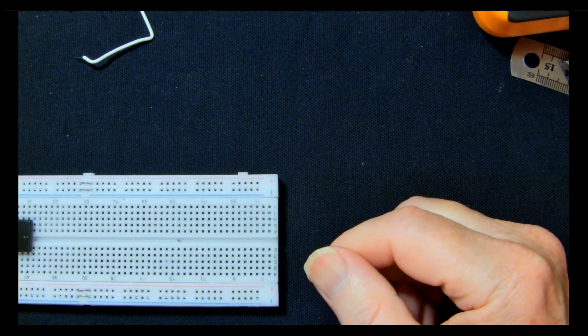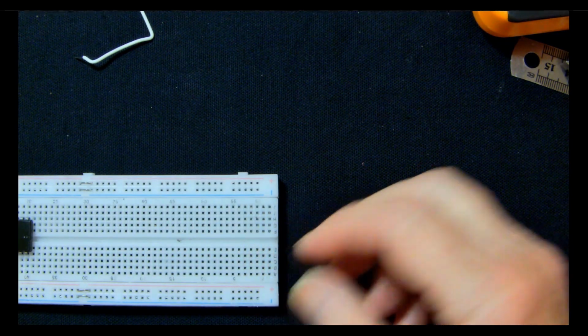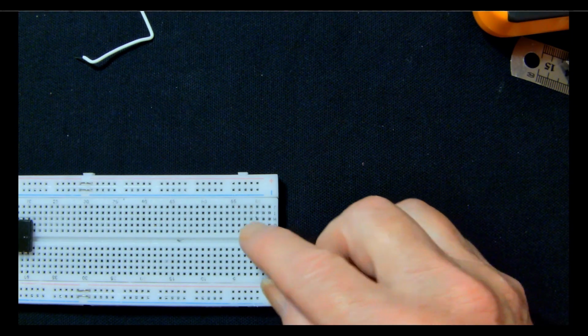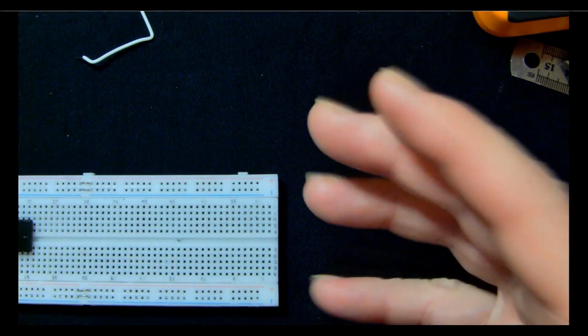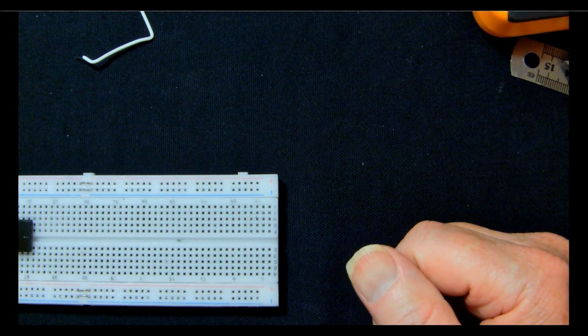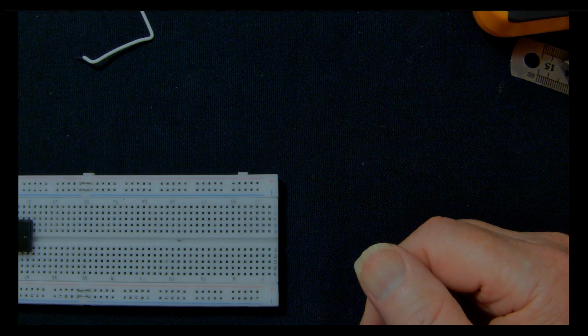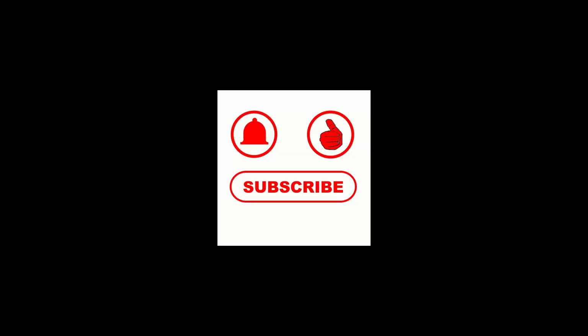I think in general though, if you're going to do it on a breadboard, you need to build it on something else and plug that into the breadboard, so that you're not using the breadboard circuits itself to actually enact the circuit that you've designed. If, however, you're using a microcontroller dev board and you've just got it plugged in, you're probably not going to have any of these problems. If you're just using it for output and input and then using a display and stuff like that, you'd be absolutely fine.